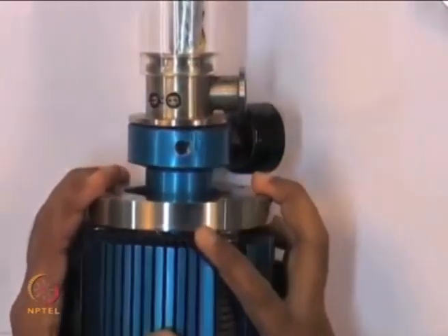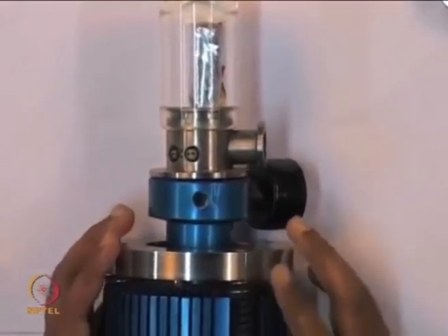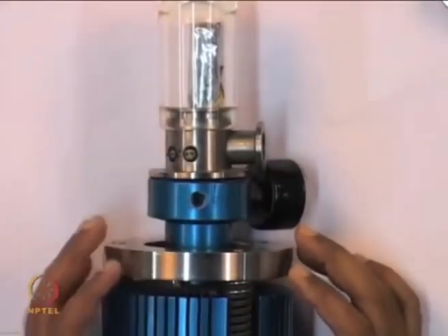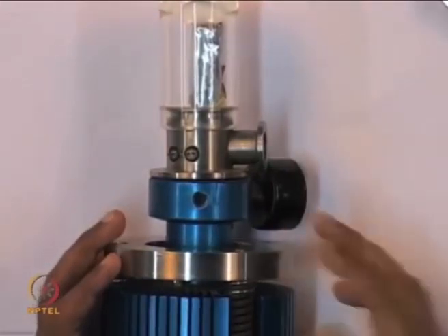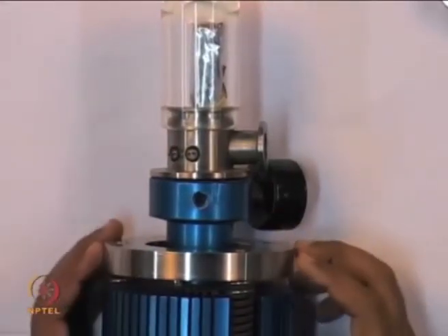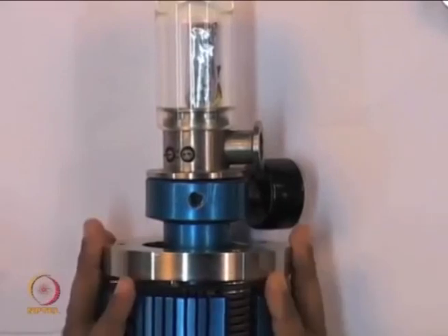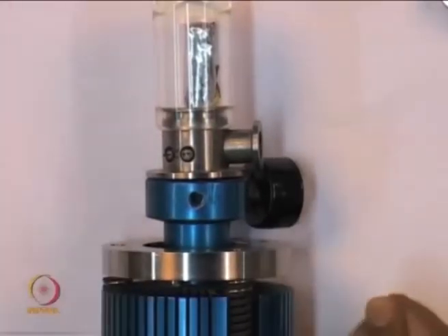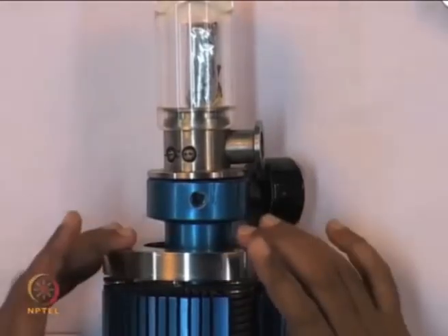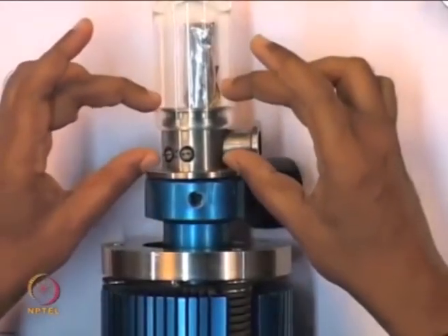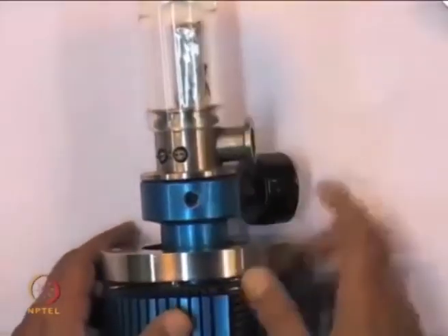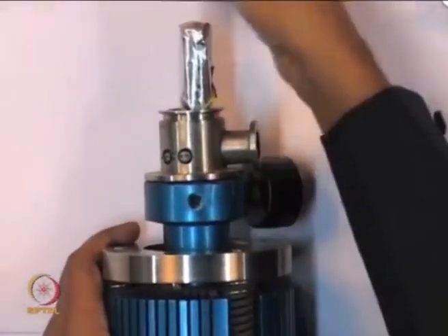The way you see in a domestic refrigerator, you have a compressor at the bottom and an expander, which is actually a capillary tube. Then you have different heat exchangers also. Similarly, this cryocooler, which is nothing but a refrigerator that produces very low temperature, also has a compressor. There is a heat exchanger inside this, and there is an expander at the top. Now, I will show you what it is here.